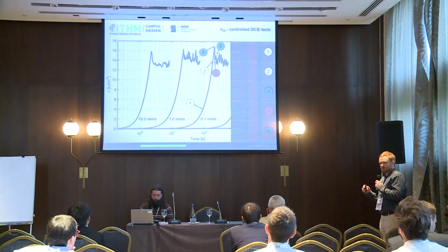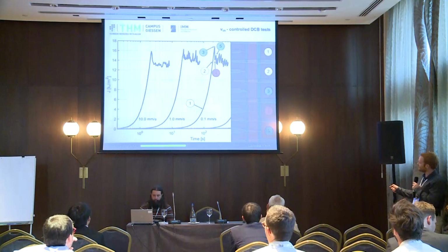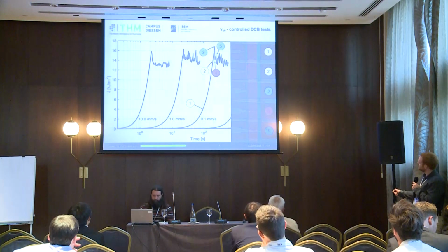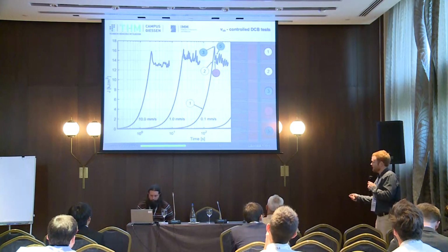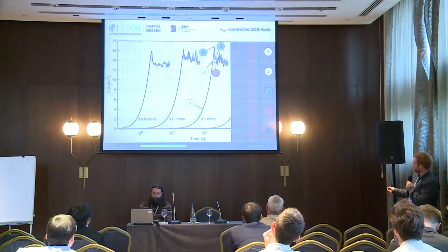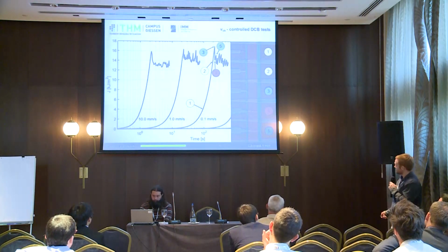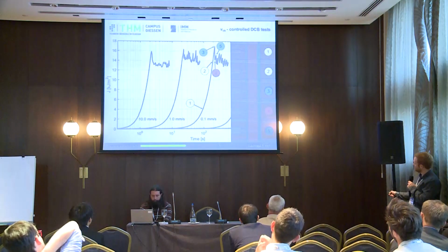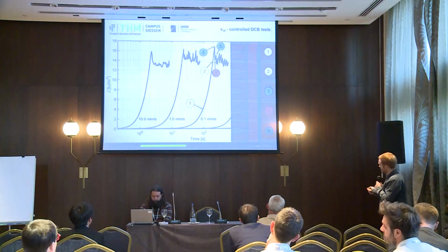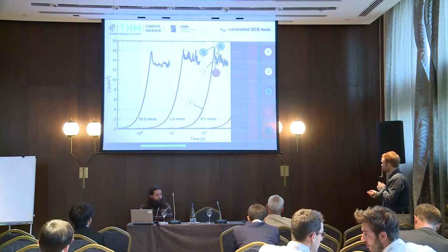And this is unexpected, that we have crack propagation before reaching the fracture energy, before we reach the maximum value, but we've seen, colored in blue here, subcritical growth. And at the point of maximum J, the crack is jumping. So crack propagation gets overcritical. This is what you see with this falling region here. And at picture 4, crack propagation changes again from overcritical to subcritical, anew.